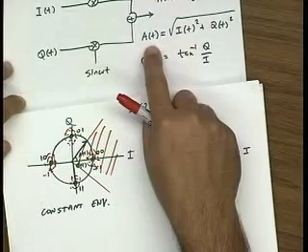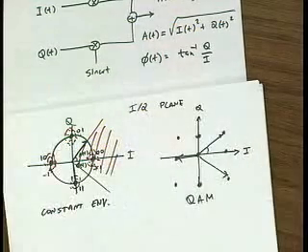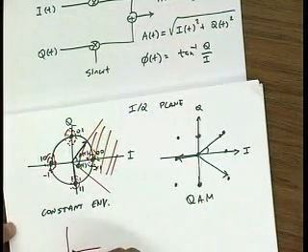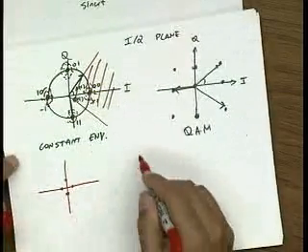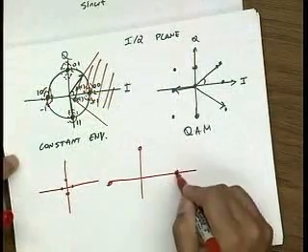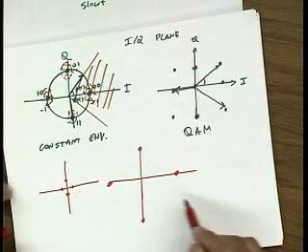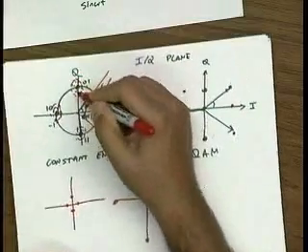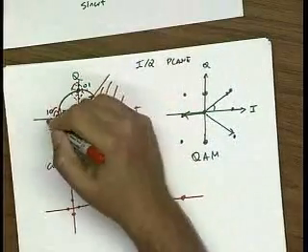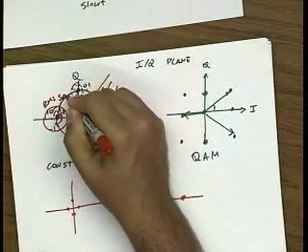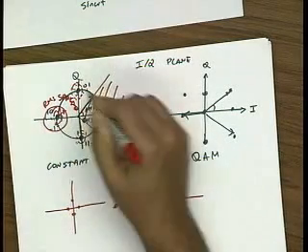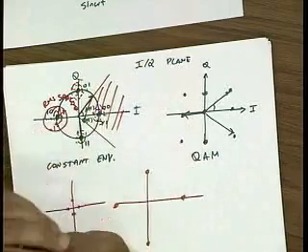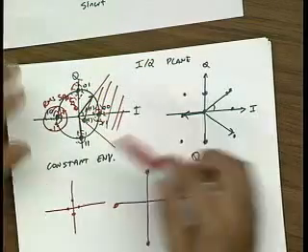So if I wanted to reduce the probability of error, I would basically scale this. I would send A of t, which is bigger. So in other words, if this were the original constellation, I would do much better to send this constellation, right? Because now the probability of error is much smaller. And of course, the amount of spread, the RMS value of the spread here, is related to the amount of noise in the channel. And so you can see that signal-to-noise ratio plays a big role in determining when you make an error.